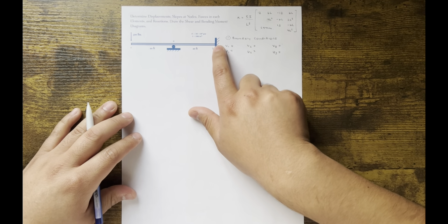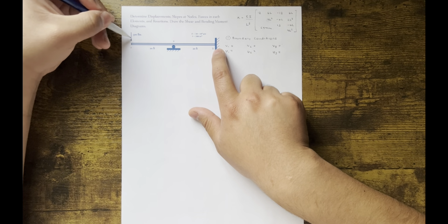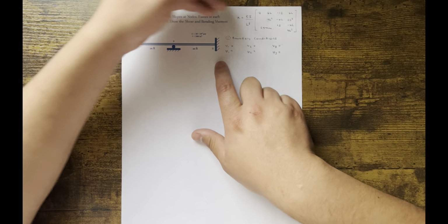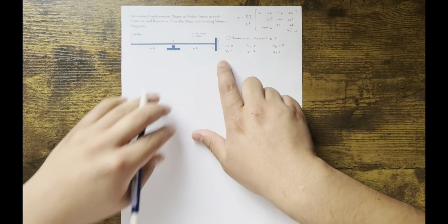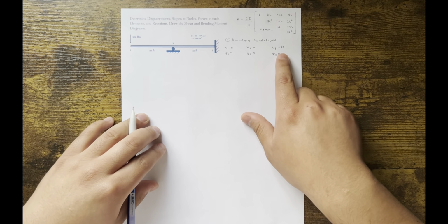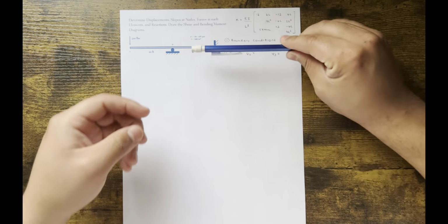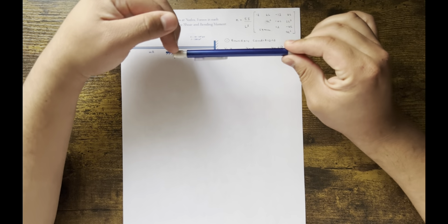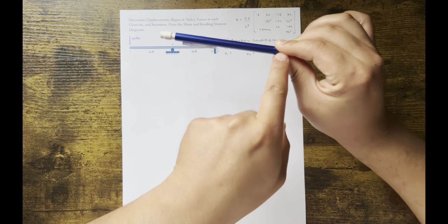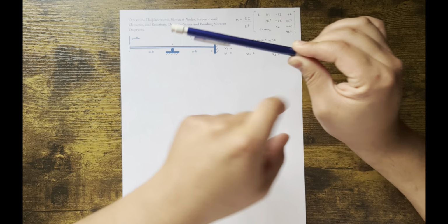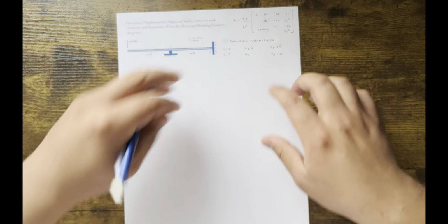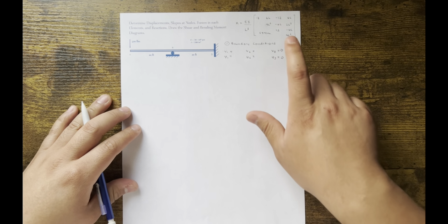But in this case, look at V3. If you apply a force here, you're never going to move this, it's fixed. So I know for sure V3 is going to displace 0 in the Y direction. Same with the angle. You could apply a force here, but this thing is so stiff at this location that it's keeping it so straight that the angle is always 0 in this case. And you should know this from statics. So these two are 0.